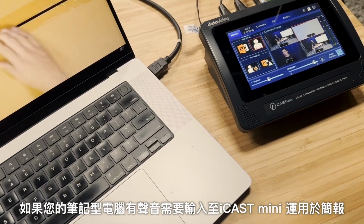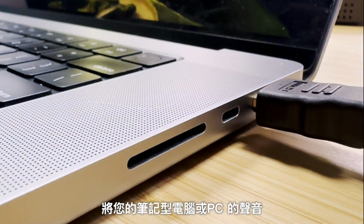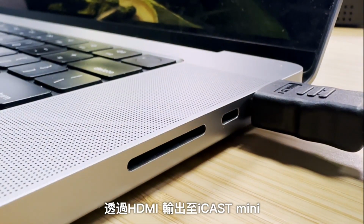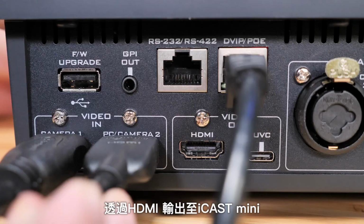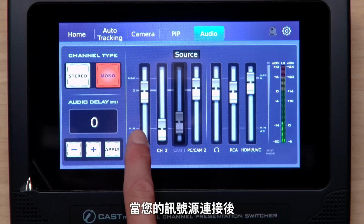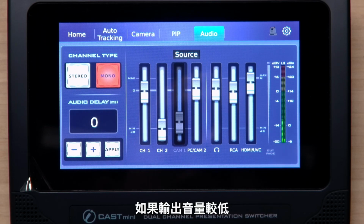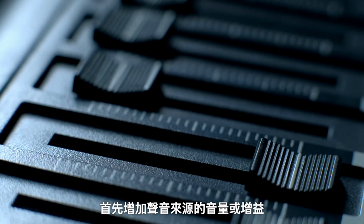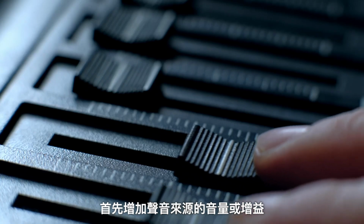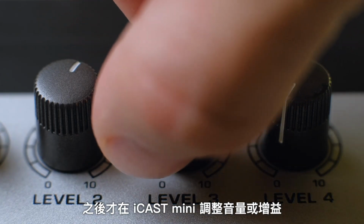If your laptop has audio that needs to be played into the iCAST Mini for a presentation, set your laptop or PC to embed the audio into the HDMI output, and the iCAST Mini will recognize it. After your sources are connected, play test audio into the iCAST Mini to adjust levels. If levels are low on the iCAST Mini, first increase the output levels and gain on your audio source before adjusting the gain levels on the iCAST Mini.